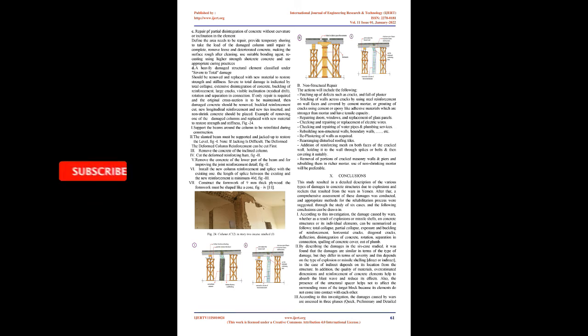D. A heavily damaged structural element classified under severe to total damage should be removed and replaced with new material to restore strength and stiffness. Severe to total damage is indicated by total collapse, extensive disintegration of concrete, buckling of reinforcement, large cracks, visible inclination, residual drift, rotation, and separation in connection.